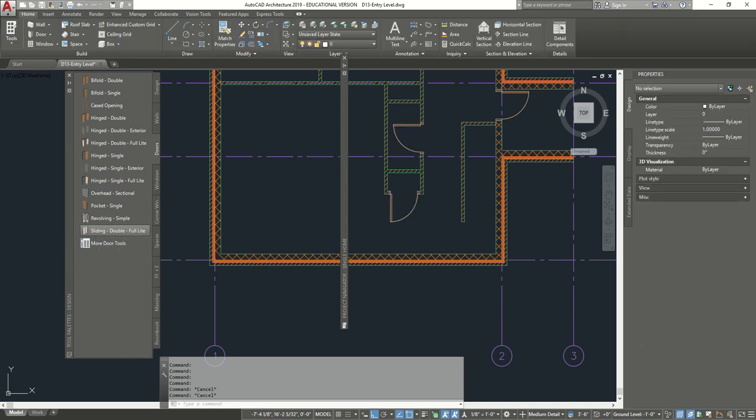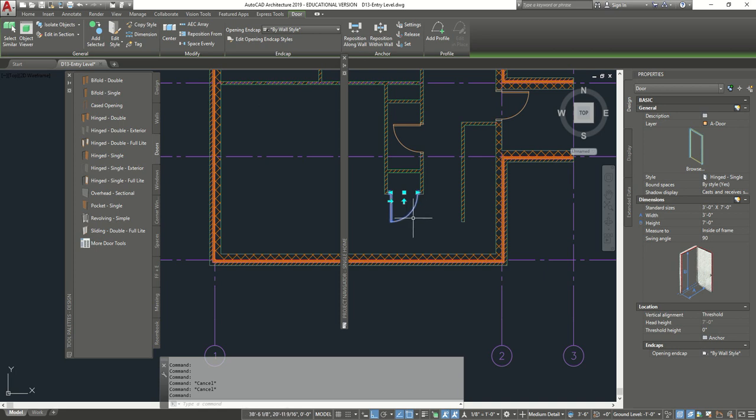So now we're going to do some customizing of a door. We're going to modify the door right over here. So I already showed you how to flip using the grips. I showed you how to change the swing direction. Now I just want to show you how to change the size of a door. So we have the door right over here. We're going to go now and change it. See? Right now it's 3 by 7. We could go here, click on the width, and actually just type in 2'6". And what's that going to do? It's going to make our door smaller.